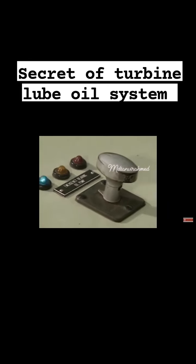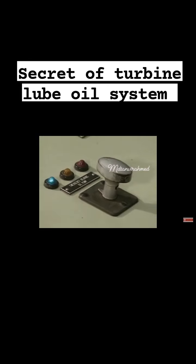The pump is not in the standby or automatic position. It will not start automatically when it's needed. If the pumps fail to start, the bearings may not receive lubrication and damage could occur.